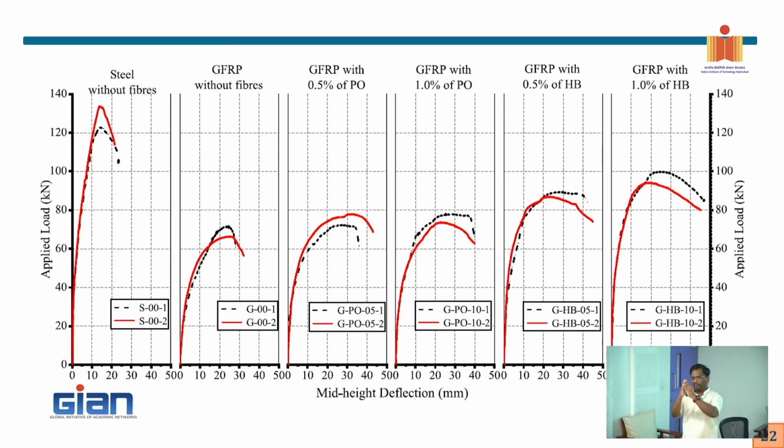If my crack width becomes larger, then what will happen? The fiber will completely pull out. So it's not that if I put in fibers, they will be effective till ultimate. At ultimate, when you have a large crack width, the fiber effect will not be there. It is only delaying the crack, and it is helping me because the compressive stress-strain response is also getting altered, right? But the efficiency of the fiber will come down close to ultimate. That's the point I'm trying to make.